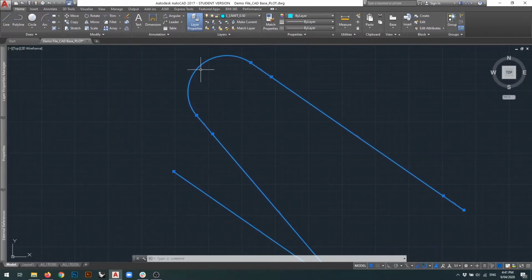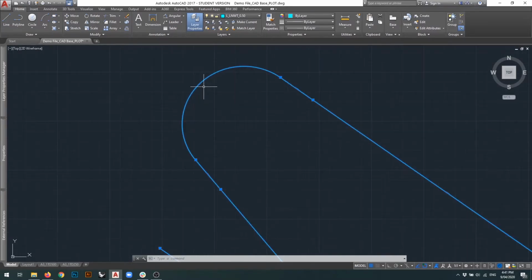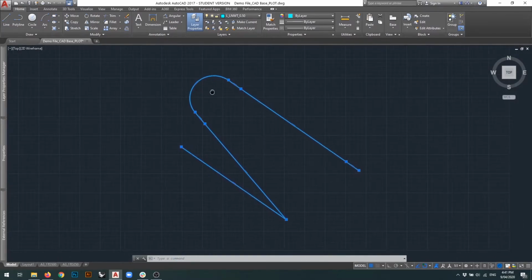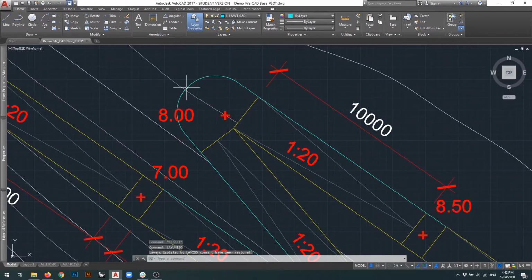That means if we import this into 3ds Max, we might run into some problems, like it may not be able to bevel it, or you may not be able to extrude it, or the boolean might have some issues. So how do we make sure that it doesn't happen? Basically we need to make sure this center point will become an end point or a grid point.